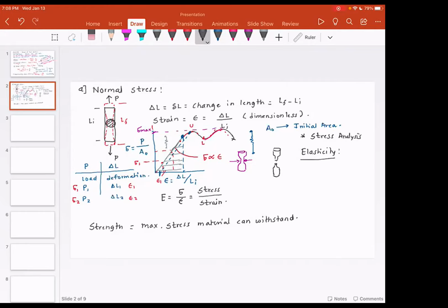So if you think about the macroscopic effect, and this is something that you probably studied in 343, if you let the material unload in the elastic region, it will go back to its initial position. This is true in general sense, but there is the effect known as ratcheting. And that is called stress ratcheting. So what happens is, even though you are cycling, a teeny tiny effect which may not be significant gets accumulated at the material level, and over a period of time that gets accumulated and the material behaves differently.